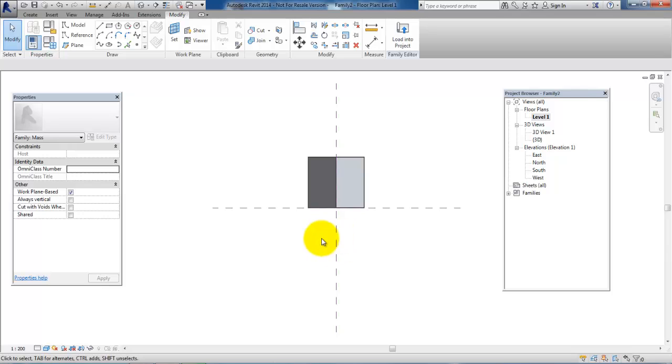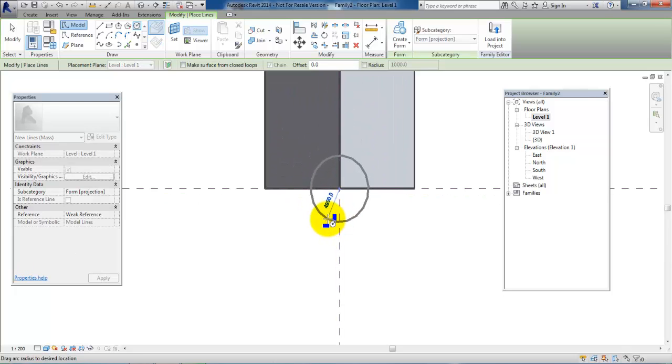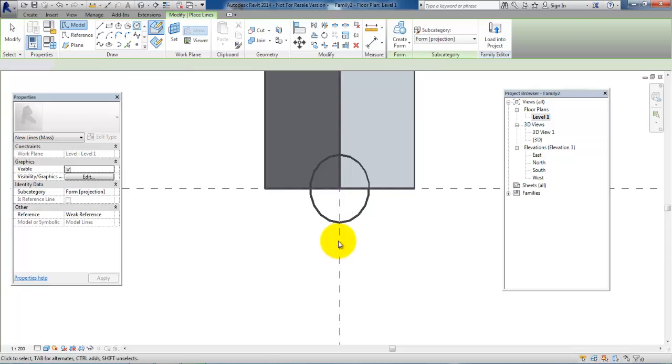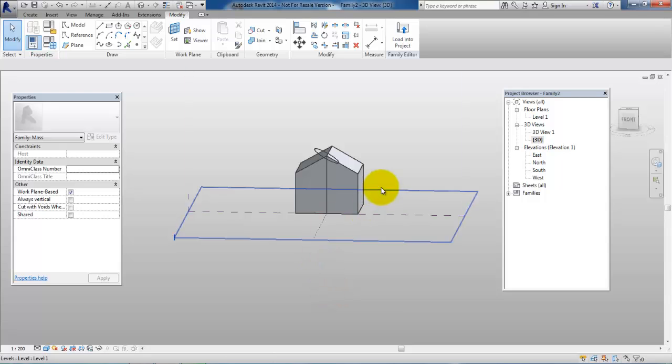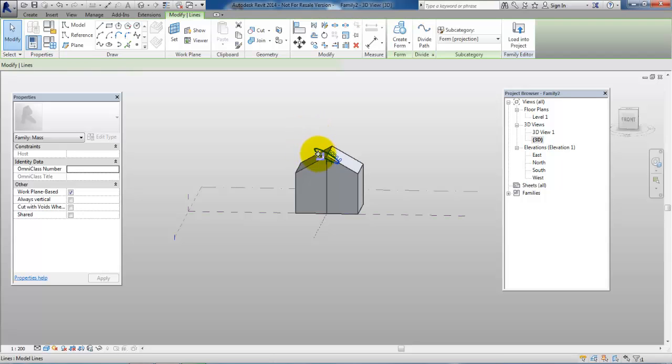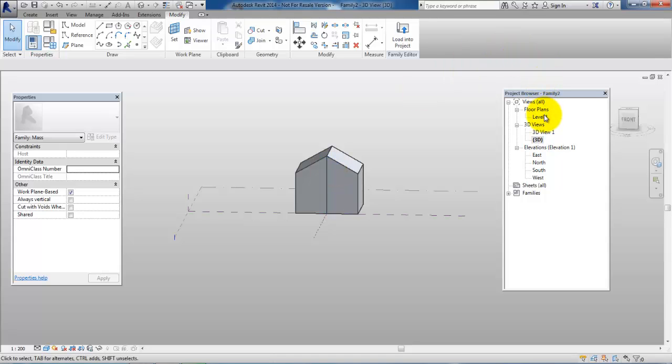And you can add more elements. Let's say I want to have a staircase out here, a circular one going halfway through the building. Let's make it 5 meters. Hit escape twice. Let me go back to the 3D model. And you can see this one has been drawn to the roof, but I actually wanted it to go to the floor. So I'll just delete this one again and go to the plan view